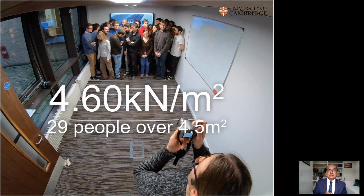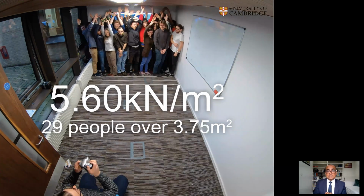Then we have 4.6 kilonewton per meter square, where 29 people are standing over 4.5 meters square. Then we have 5.6 kilonewton per meter square, 29 people over 3.75 meters square. It means that now they have to raise their arms to fit in. On a typical busy day, this will be the London Tube. When you are traveling to central London, you will have to stand like this.